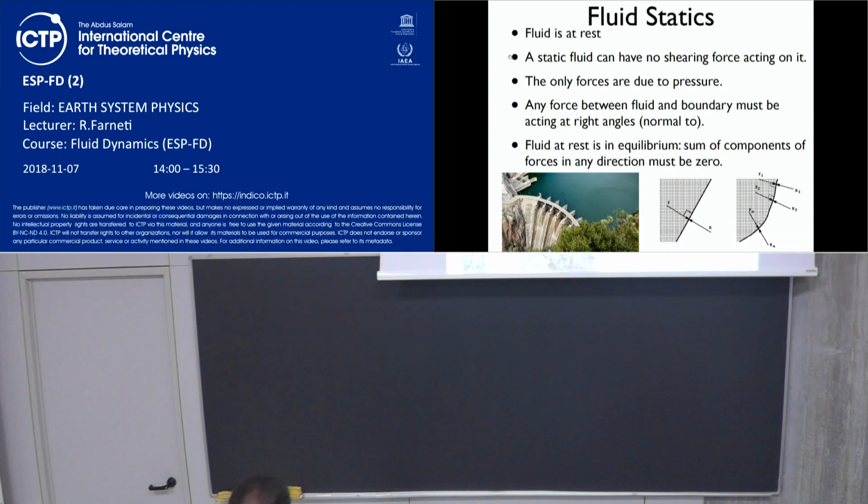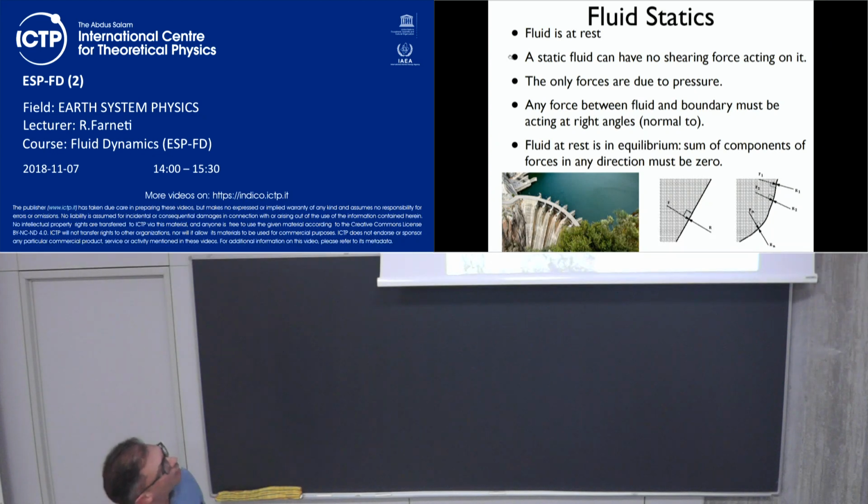Statics, okay? So statics, as the word says, is when a fluid is at rest, so there's no acceleration to the fluid. A static fluid doesn't have any shear force acting on it, right? So there's only normal forces acting on the fluid, otherwise with the shear stress there will be a deformation of the fluid and an acceleration of the fluid.